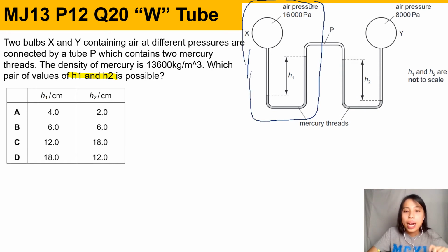Okay, part 1 there. Pressure on the left side. By the way, I'm going to choose this level because this is where things are different. Here, left side is air, right side is mercury, sorry, not water. So the pressure on the left side is just because of the air pressure there. So pressure on the left will just be 16000 with reference to this dotted line.